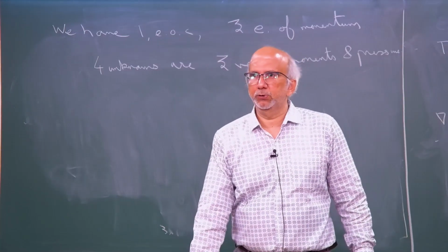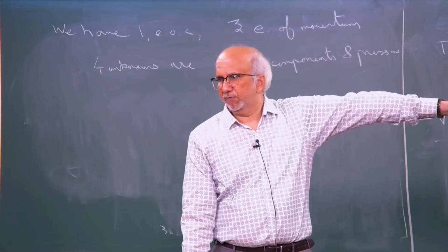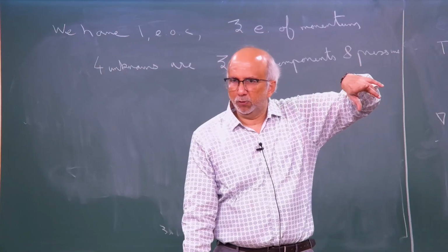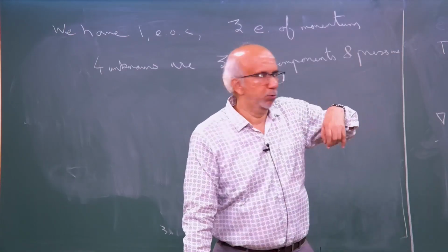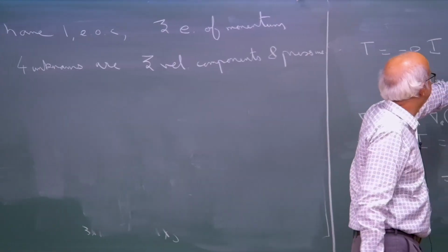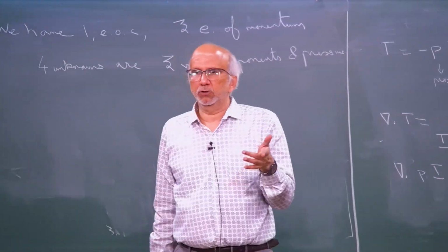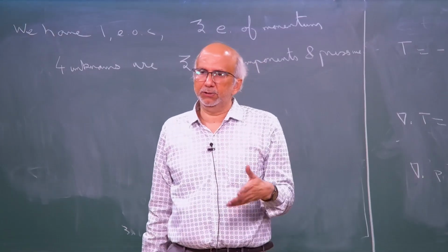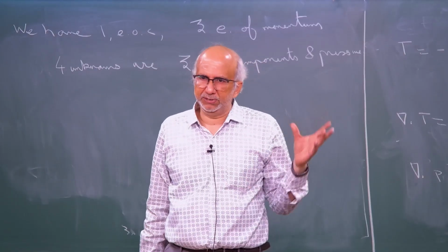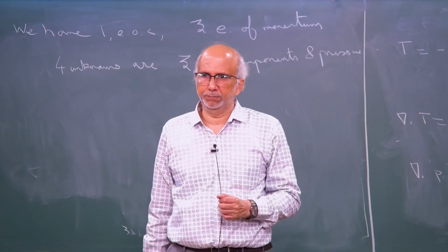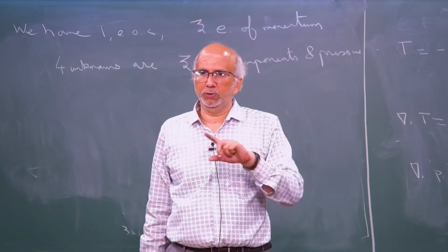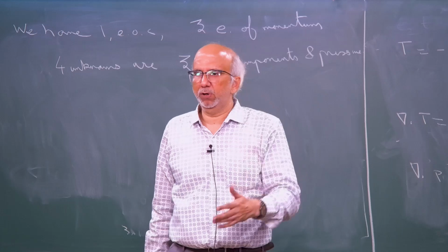But there is a small issue here. In doing all of this, there is one more tau which has come up. This tau, the stress tensor, is an additional variable now. So, in the process of deriving the Navier-Stokes equations, I have gotten one more term, and what I want to do is close this whole thing. I do not want to keep adding more and more unknowns.